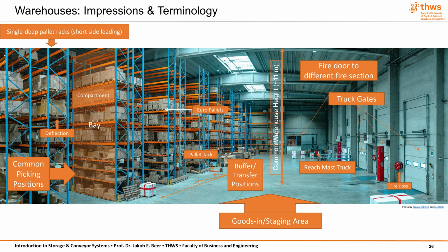One option is to increase the number of truck gates. A better option, however, is to schedule truck arrivals so that they are more evenly distributed throughout the day. Increasing the number of truck gates comes with certain side effects. First, you need a wall long enough to accommodate all the gates, which may constrain the shape of the building you can buy or build. There are often additional constraints, such as the size of the land lot or the need to position gates in specific areas to reduce noise for nearby residents or because of the location of roads.